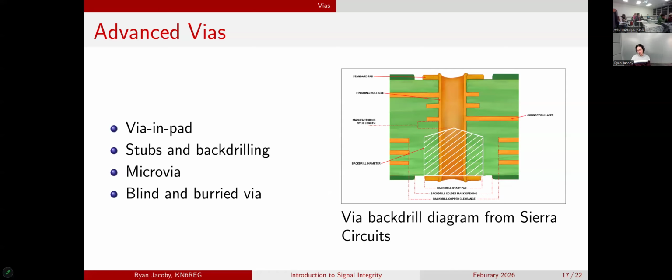ringing or otherwise unwanted stub behavior. Also, as I mentioned, vias are generally drilled through your board, right? This limits the size you can make them, especially as your board gets thick. Drilling really tiny vias gets really technically difficult, and also drilling into some materials can get very difficult. The materials can get gummy. There's lots of mechanical engineering problems, manufacturability problems.